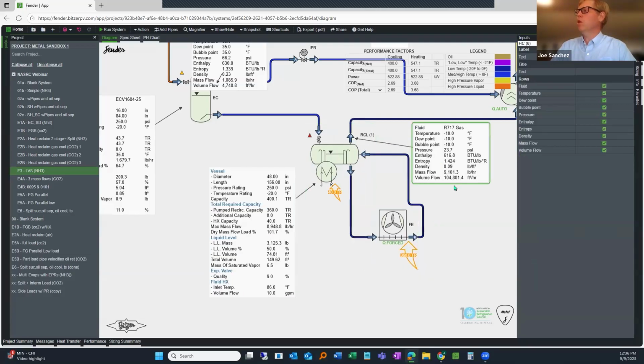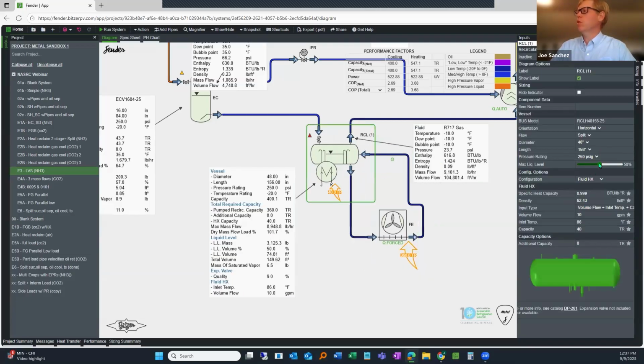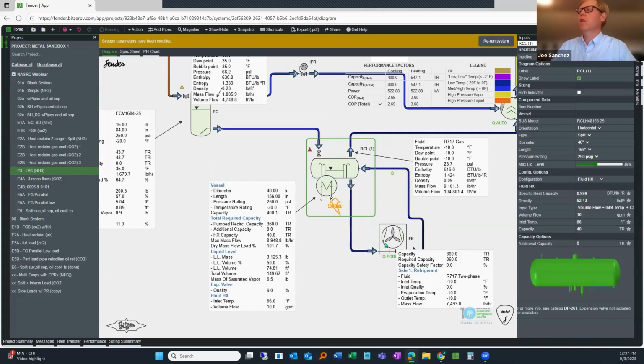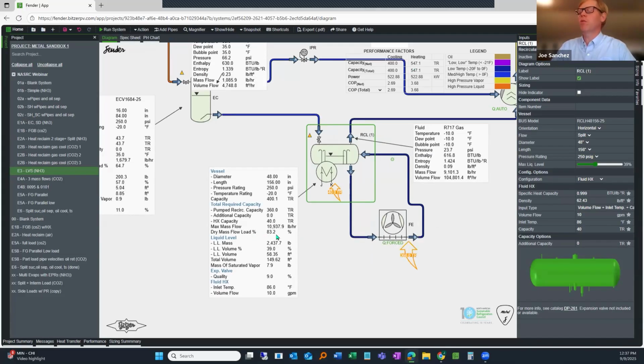So this is also cool. In this situation, we could drop the level of the vessel, because it's a horizontal vessel, and if we drop it down maybe 10%, then we can see, oh, now we have a little bit more diameter, more room for the velocity of the gas going through there, and that increases my available separation. And so now I'm only using 83% of what's available.